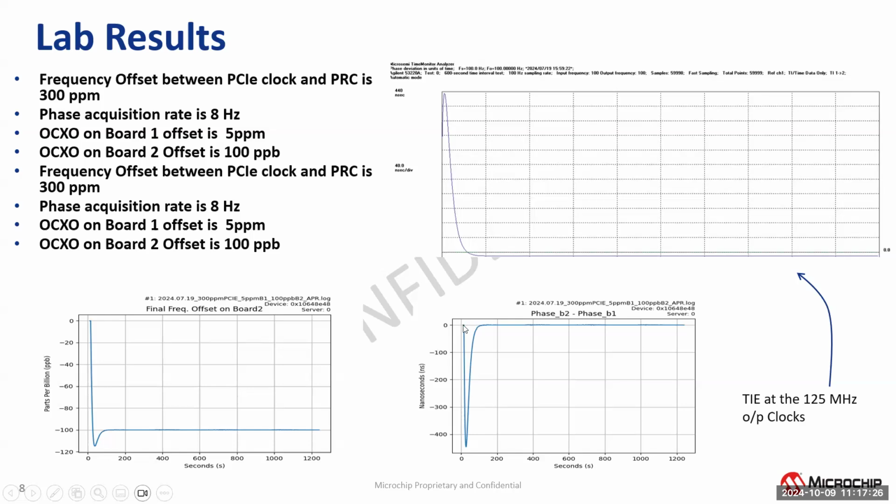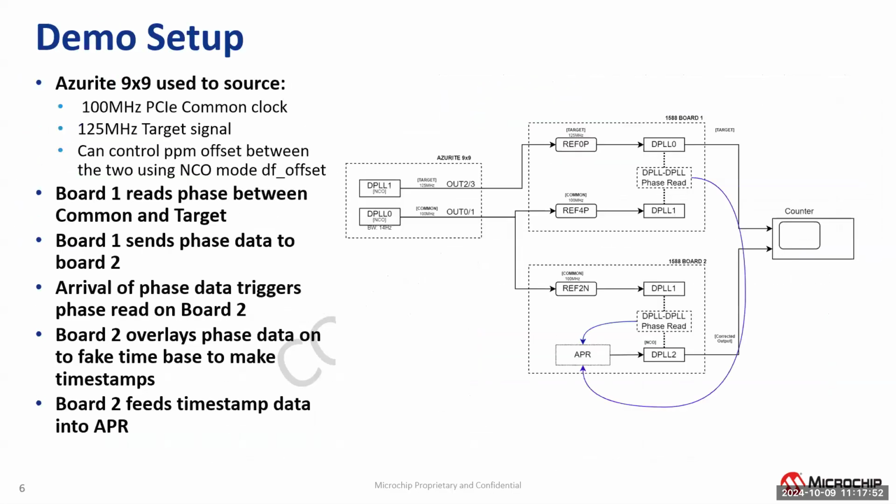So this first one is from the normalizing calculation where we subtract out that power up difference. And then after that, the first packet has the largest phase offset. And then this is the algorithm doing its work to reduce the phase offset by adjusting the frequency on the NCO PLL at the output. And that's sort of the concept in a nutshell.